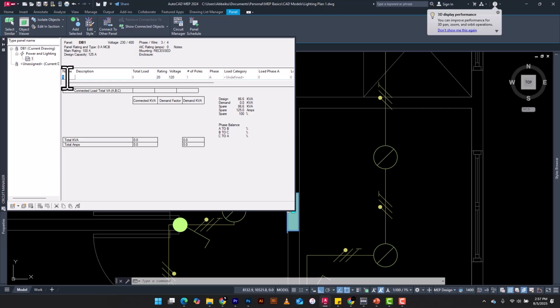All right, so I'll go ahead and call this circuit bedroom 1 and 2 lighting. Sorry about that. So this is the name of the circuit, and this should be L1. You can choose to name this T1, you can choose to name this V1, you can choose to name it whatever you want, but I choose to call mine L1, and it relates more to lighting. L1, lighting circuit 1.